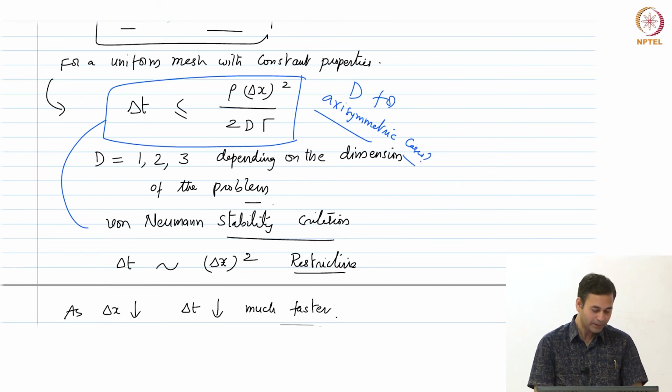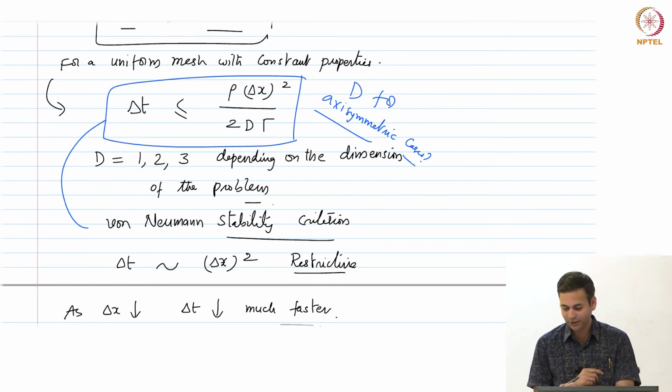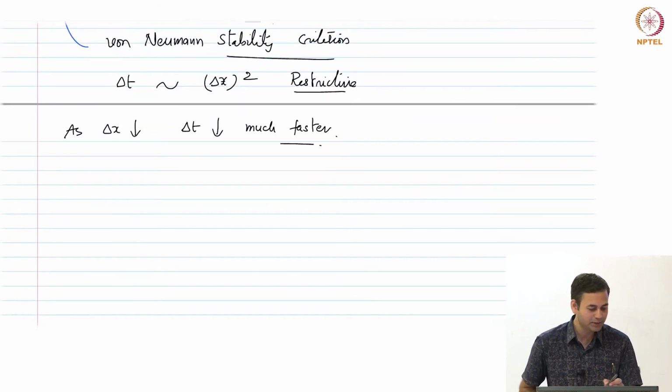Now I have one question. Let's say we have no iterations, which is kind of good news. So why don't we solve every steady state problem using unsteady with this explicit scheme? Why should we bother ourselves to write this TDMA, line by line TDMA, all these things, or Gauss-Seidel? Or can't we just pretend that all the steady state problems we want to solve are unsteady, add this extra term, and start using this explicit scheme? Wouldn't that be easier? Wouldn't that be faster?